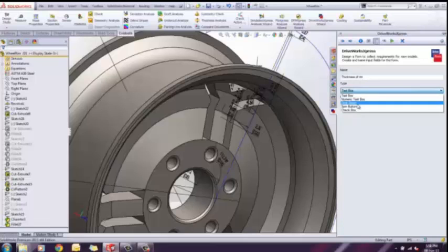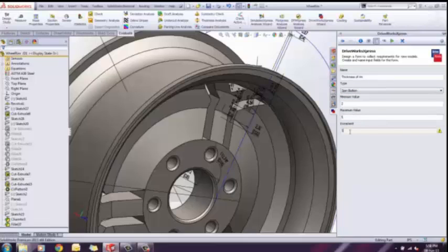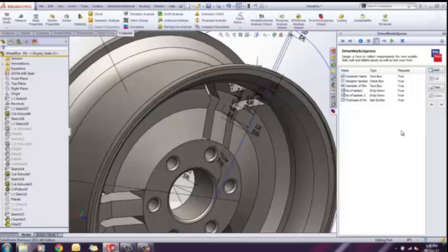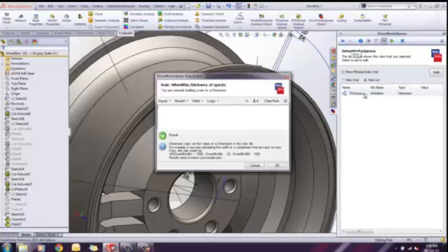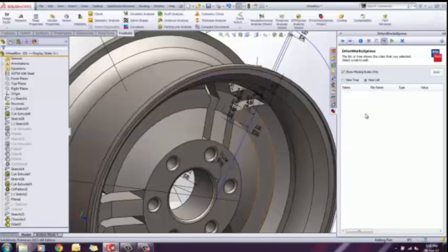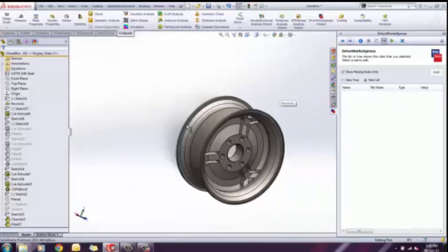Then I'm going to apply a spin button increment, where I can specify the minimum value as 2 mm and the maximum value 6 mm as the thickness for a sprocket. Okay, and it will be incremented in intervals of 0.5. Next, this is again the rules tab actually. Here you can see I'm going to define a rule for this thickness by taking an input from this thickness.